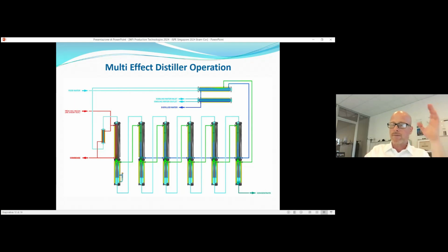Also in this case, I'm talking about what we think is optimal, so as not to have too high a consumption of cooling chilled water. It is clearly possible to reduce the temperature to 90 or 85, but we think that, considering there is the looping system with an exchanger, it is better to control the temperature in the looping system. Again, to balance the consumption of cooling water.